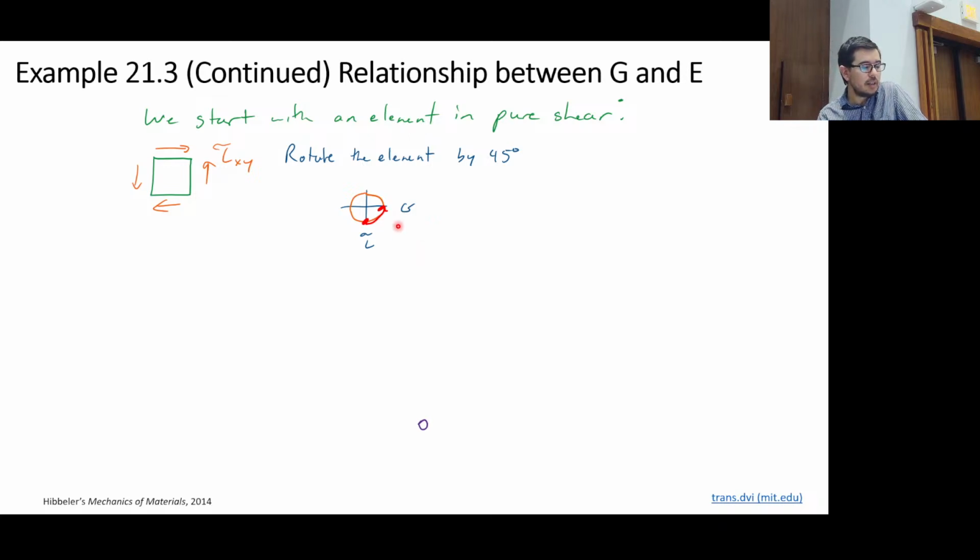In this case, what is tau equal to when I've rotated on Mohr's circle here? So now I have this new state. It's a mini Mohr's circle, I understand. But in this state, first off, is this a state of principal shear, or is it a state of principal normal stresses? Or is it a state of maximum shear stress?